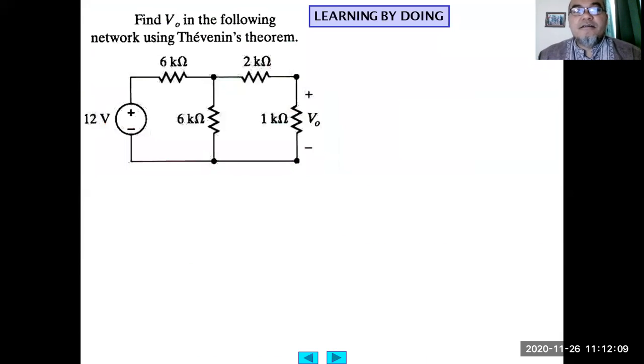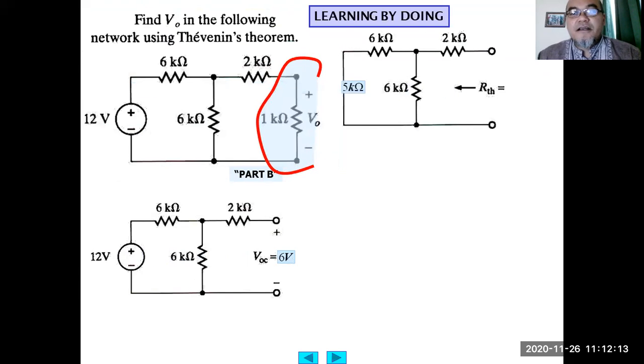I hope it is quite clear for each of you how, when you are given a circuit, you can determine the Thevenin equivalent circuit or Norton equivalent circuit. It's a matter of choice at which part of the circuit you would like to make a partition. If you want a straightforward calculation of the output voltage or current across a certain load, like a resistor here, you can immediately cut at the end terminals of that load component.